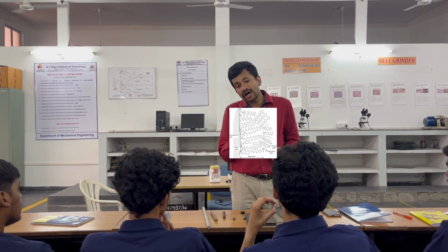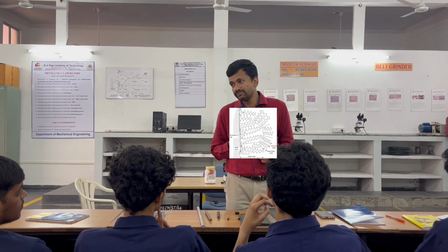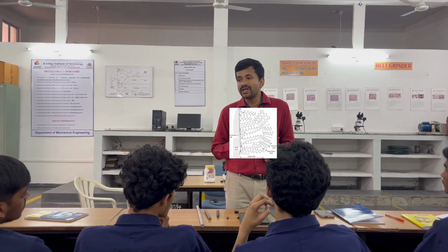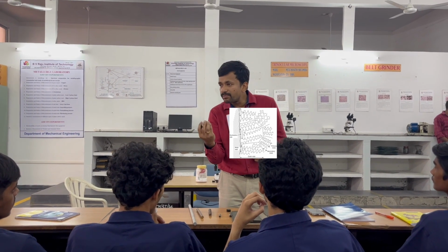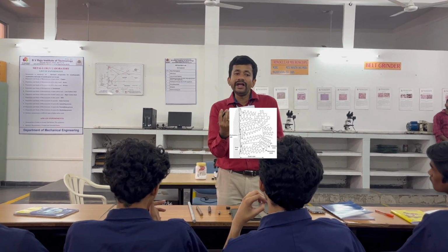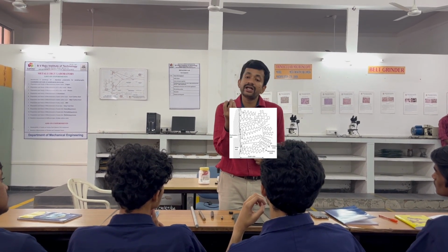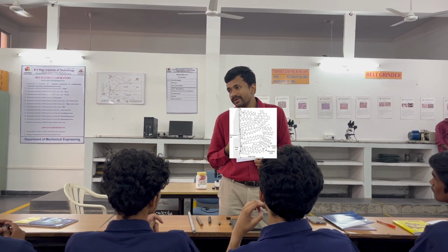When it comes down, they will start forming what are called nuclei. At some places it starts forming a nucleus, which is nothing but the atoms coming closer to each other, and this becomes the center for further cooling and further joining of the neighboring atoms. That's how the nuclei are formed.